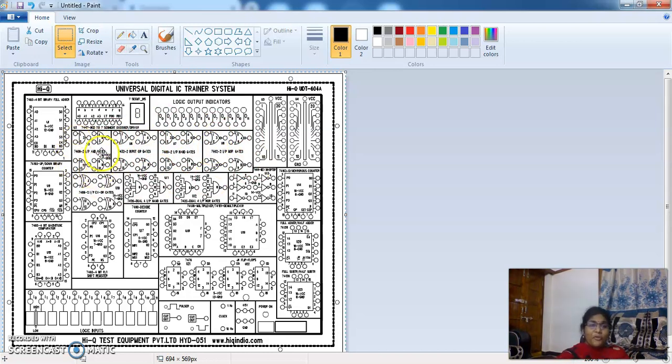So for conducting the first experiment, second experiment, third experiment, fourth: realization of logic gates, realization of full adders, half adders, realization of flip-flops. So first see here, for realization of flip-flops, for example if you observe the JK flip-flop, you need to give 3-input NAND gates. You need to give 3-input NAND gates, right? So for that you need to take these 4-input NAND gates.